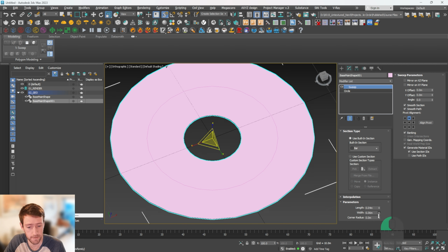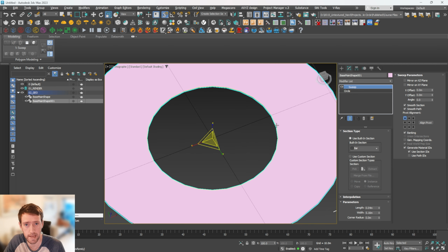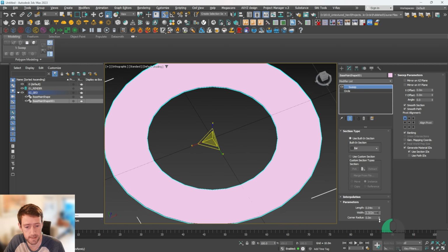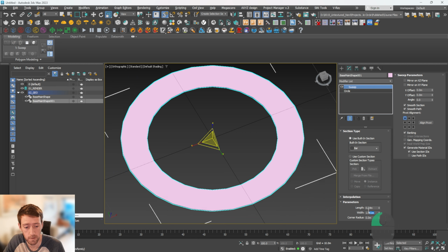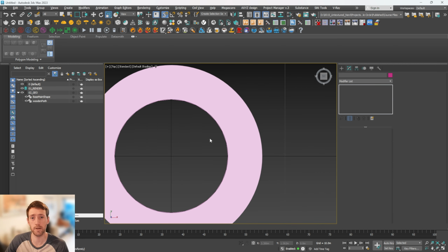Now the width itself, if I start changing this, you'll see it's going from the center there, which we don't want. So we need to change the pivot to top corner and you see that switches to that edge of that spline. So we only want a short path. We want around 2.5 to 3 meters. So basically you want about 3 meters because you want two people to be able to walk abreast. That's how I deal with paths anyway. So we have a wooden path.